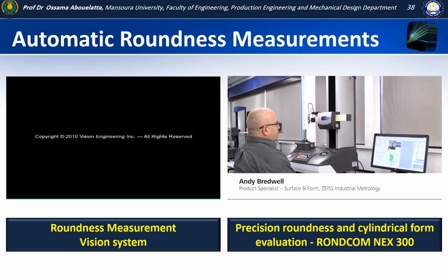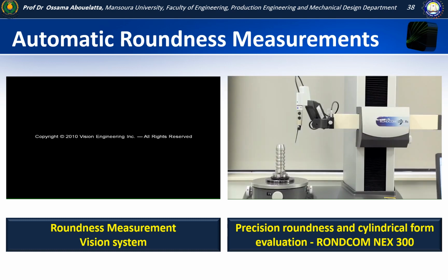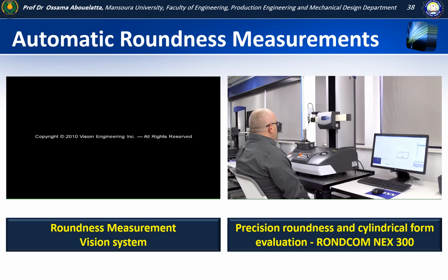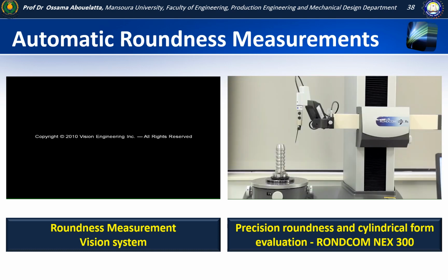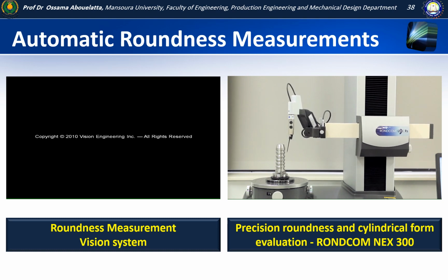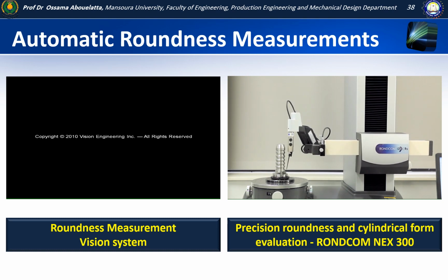Hello, today we're demonstrating the Roundness RS300 and some of the CNC capabilities. This machine has the ActiPro software, which will be running and managing this machine. From here we move into a part alignment. The Roundness 100 is a manual alignment, but the Roundness 200 and 300 series have automatic programmable alignment for centering and tilting with a wide range.